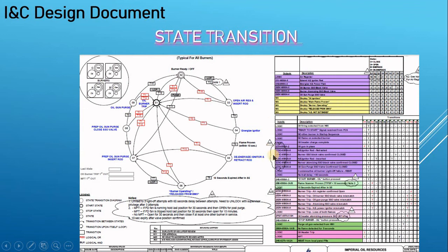So you explain exactly where you go from one state to another state. Sometimes you give the data about each state: what's happening, which valves are open, which valves are closed, and where you go from one state to another state. So assume this is your lube oil start. If it failed, then you go back to this, or you go back to trip status. So you show whatever you like in this transition. How you explain a control system in this method, in this case we have the burner. You can combine it with a cause and effect, you combine it with the narrative.